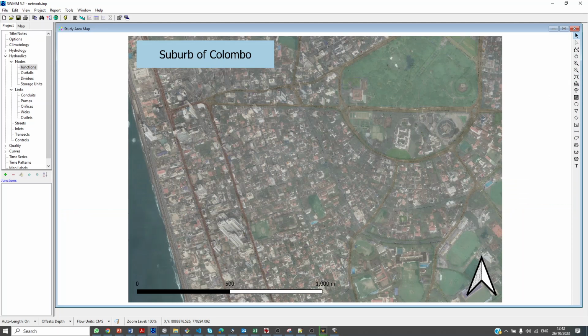So now the first step is let us create some drainage subcatchments. Usually this is done in urban areas by looking at different blocks and in what direction the water would flow and so on. But for this exercise, we are going to follow our instructions. So let's start with subcatchment 1, S1 here.